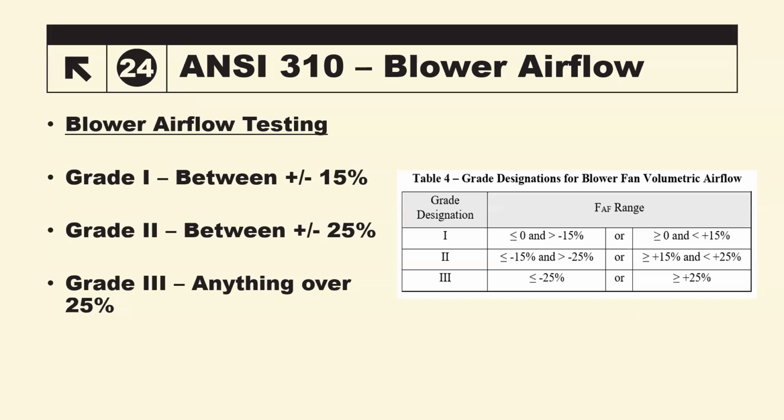You could do that if you've got a lot of leakage on one side or the other. But if the system was completely airtight and you're just transferring air around, but you have friction loss in the ductwork because of improper installation, you now have a defect in airflow. And this is where, when we're grading these and testing it, we're basically getting a report card of the system.